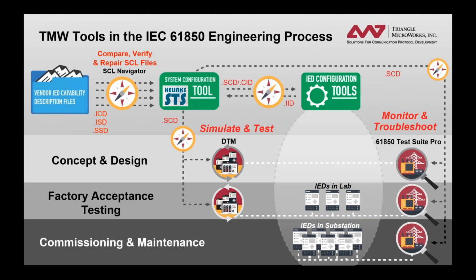How does this really work when the controller is working as a client and the relay as a server, where information goes to SCADA through the 104 protocol? So we implement both 61850 and the 104 protocol you're describing through our source code libraries. So the simulation tool of DTM isn't really just smoke and mirrors, pretending like we're simulating devices. We're actually simulating based on the stack that is out in plenty of devices all around the world, with customers who use our stack. So we actually simulate 61850 down to its spec requirements.